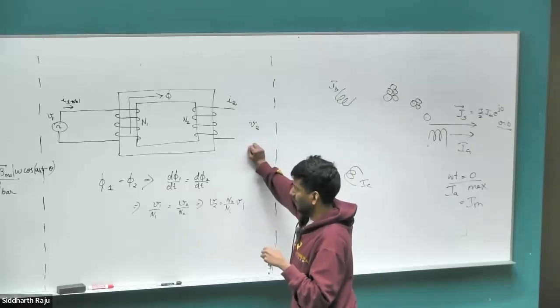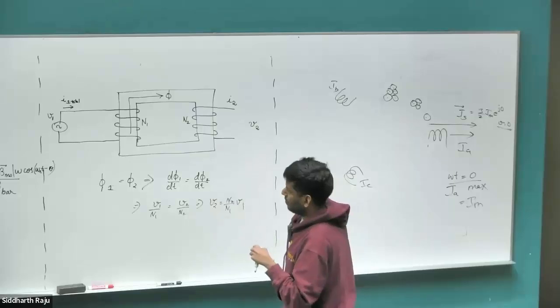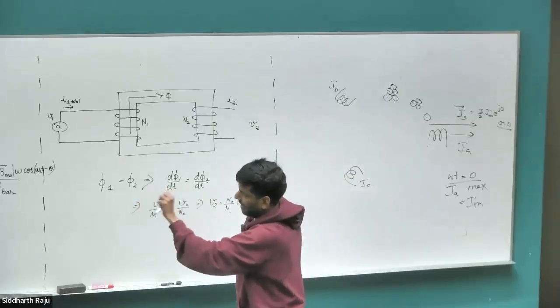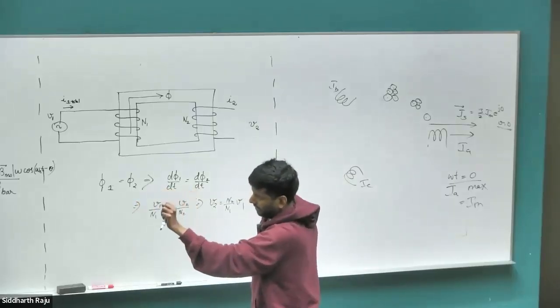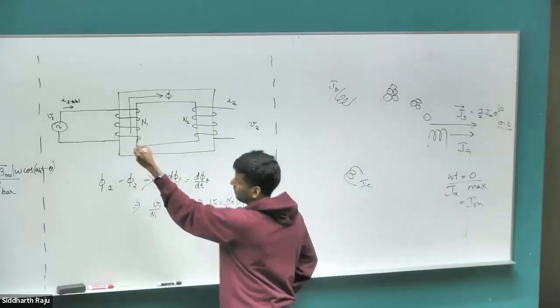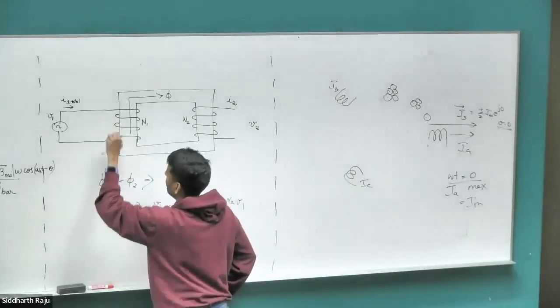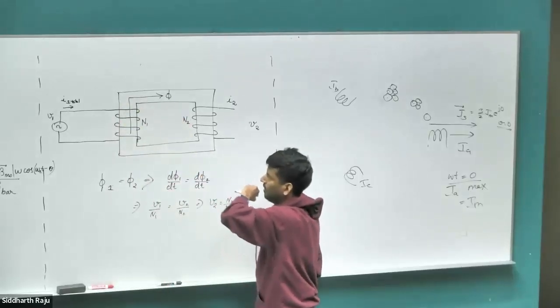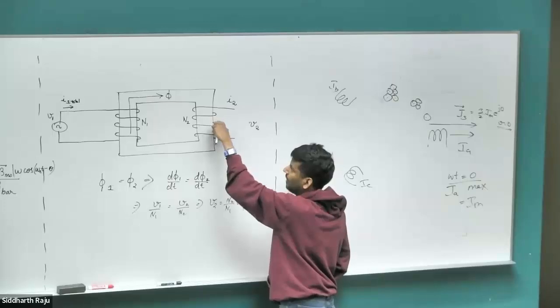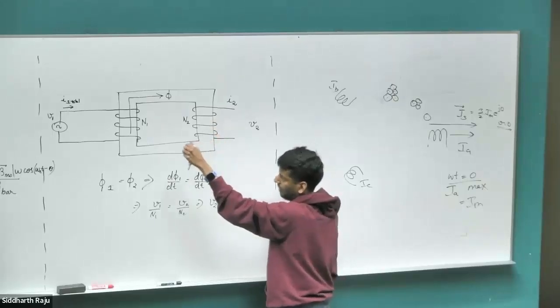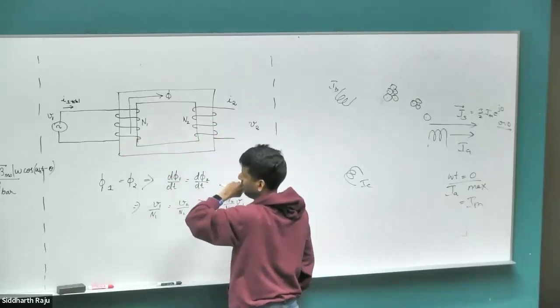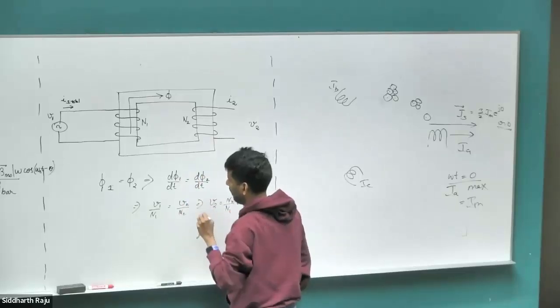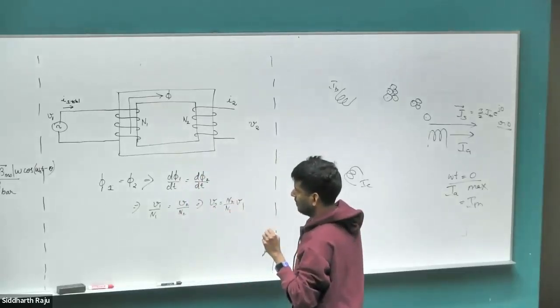Right? Everybody else? Okay. So to explain what's going to happen on the rotor side of an induction motor, let's go back to the analysis we started off on a transformer. So right now, whatever we have set up there is exactly a transformer. We have some magnetic field set up due to the primary coil, which is exactly what's happening here. I have some voltage, which is going to set up some current in this coil, and the current is going to set up some flux in this coil, and the flux is going to link to the second coil. And using the idea that the flux on this set of coil must be the same as the flux linking this set of coil for an ideal transformer without any leakage inductance.